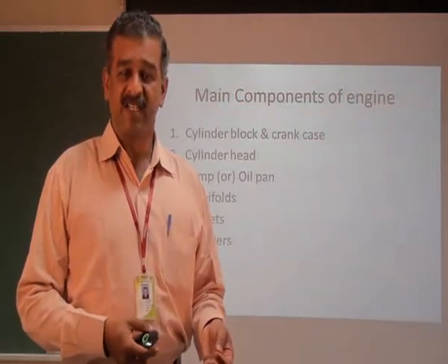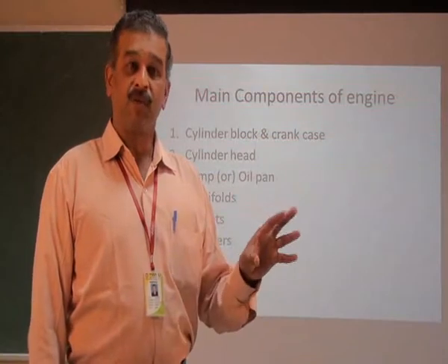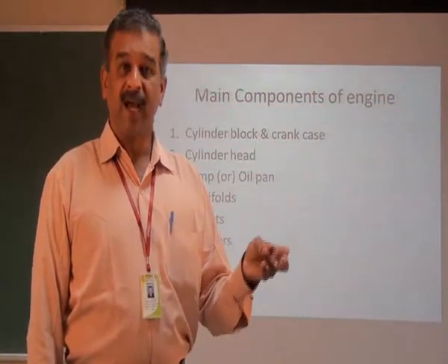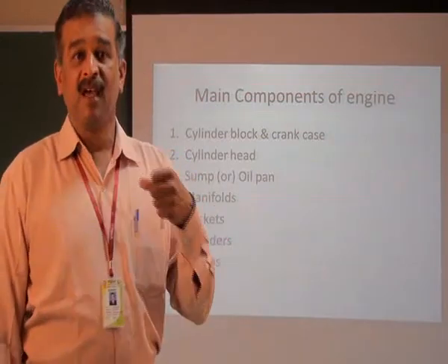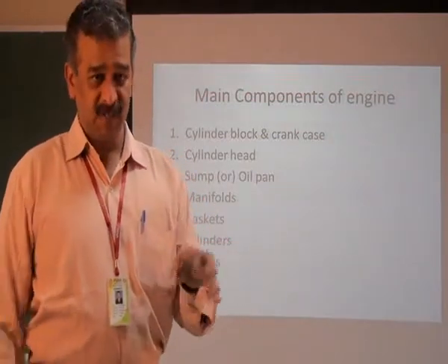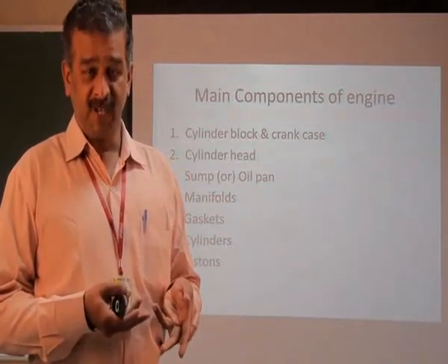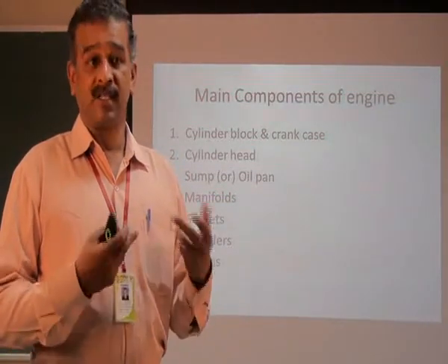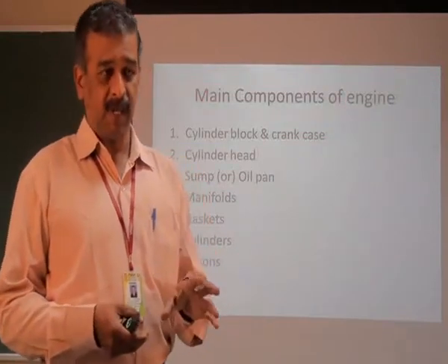As far as spark ignition is concerned, if you are going to use a carburetor, then you are going to mix air and petrol in the carburetor, and it will be fed inside the cylinder through some manifolds, some pipes. We call it pipes. That pipe is being called the manifold, the inlet manifold, or it is multi-point fuel injection also. The same principle is going to happen.